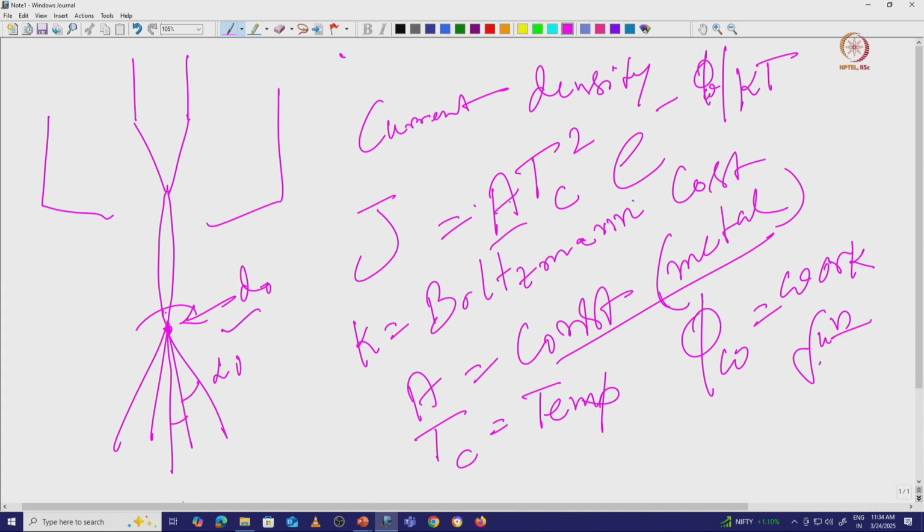If we get the proper current density, that will help us to do the rest of the experiment. Whenever we set up or install the instrument, there are a couple of things we have to pay attention to: what the emission current will be, what the bias voltage will be, and what our total current density will be.